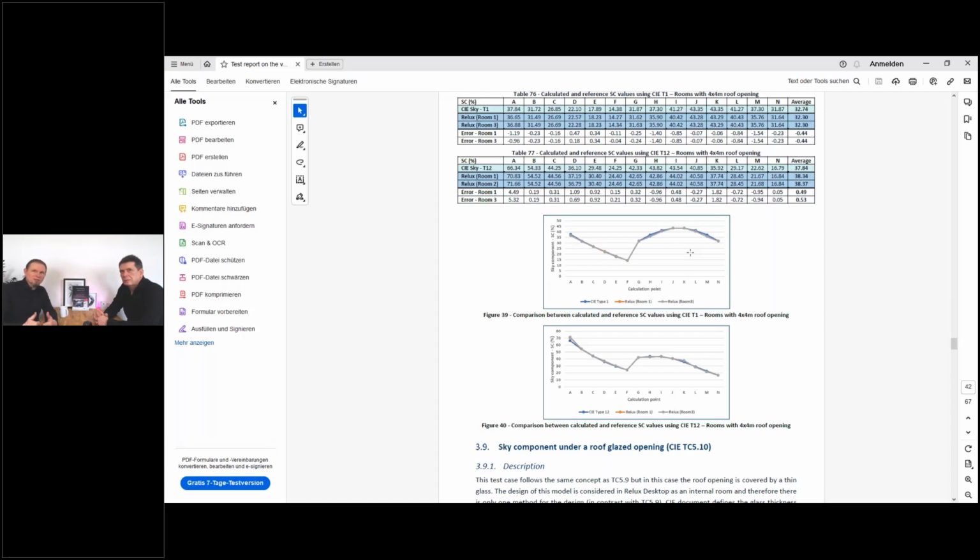So in single points, it could also be up to 40, 50, I don't know, in a distance on a single point. Yeah. In a worst situation, it may happen that you have, for example, luminaires with a less luminous flux than calculated, but the reflections in your rooms are higher than you estimated, and so you have the correct results with two errors or two mistakes inside of your calculation. Yeah, the average is helping on this.